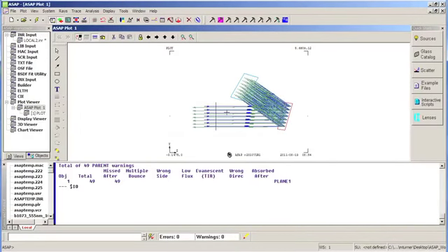So here is our first surface, which is oriented within our global coordinate system. It is perpendicular to the z-axis. But then we have these 2 reflecting surfaces that are skewed in that coordinate system. And what's happening within the ray trace is the light is passing through this first surface, reflecting, coming back and reflecting, and then passing through. Because we have a slight additional skew on this upper reflector, we don't quite have a retroreflecting system, but that's what the goal is, to show you how the light reflects back through the system.